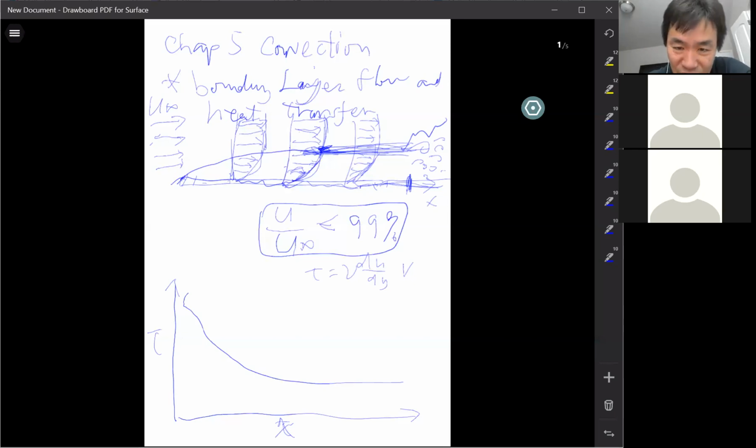Along the same location here, the shear is going to change significantly. It will suddenly increase, then gradually decrease. It's not the entrance region, it's the transition region. Suddenly the shear will increase a little bit when the transition starts. Then at the end, it starts to decrease also, if it's further longer.